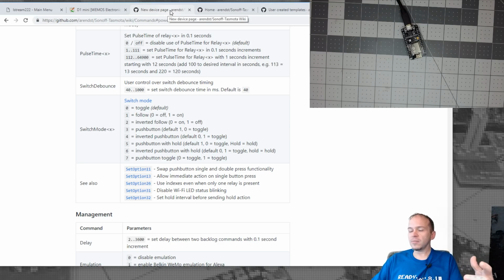I know there's the other part I've seen people struggle with, and it does take some time. In the newer development versions, not in the standard release, you can get the newer development versions of the precompiled bin files for Tasmota, and it allows you to pick all the pins for power monitoring. I know a lot of these different plugs have power monitoring, but you've got to figure out the pins and you've got to calibrate it. And sometimes it takes a little bit of time.